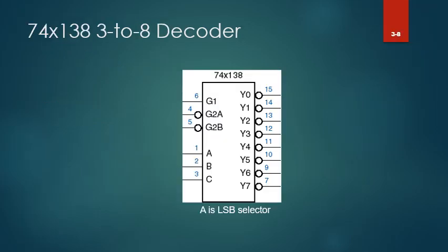So you may need to design a 3 to 8 decoder. Okay, and if you recall, you have seen this 74138, which is the number of the chip that functions as a 3 to 8 decoder. And then you find, if you remember, they have 3 enable input ports and 3 inputs that represent the 3-bit binary, and the output here could be active low, like this, or it could be active high.